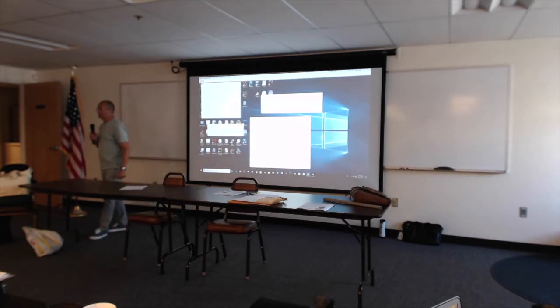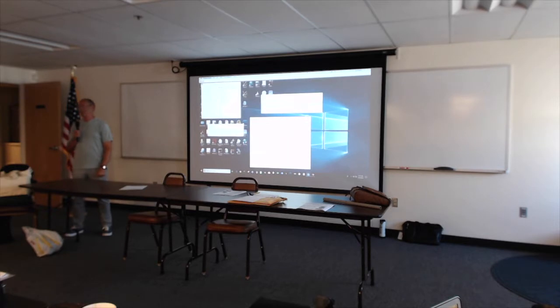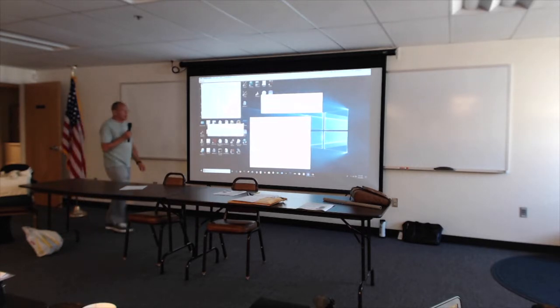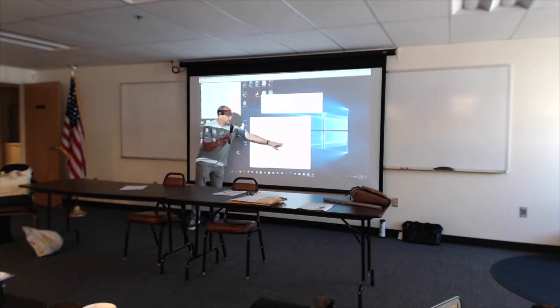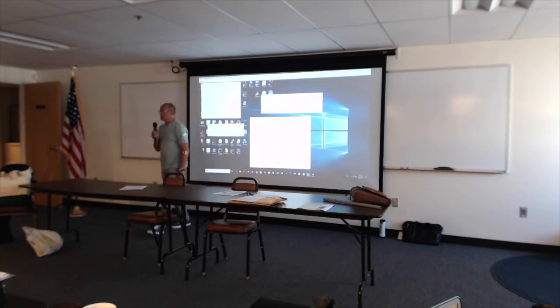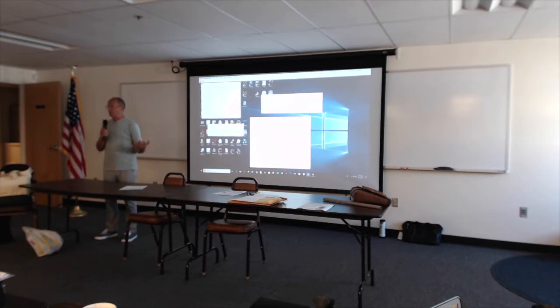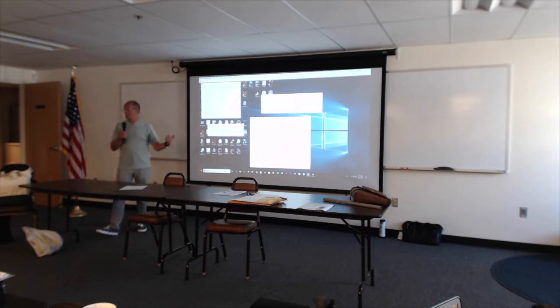Yes, sir. Tom, this may sound dumb, but was there a reason that you feed it from a corner and not from the center or the bottom? Yeah, I went through many iterations of this model, and I put the connection in the center here, and the plots just, the SWR, I couldn't get it within a reasonable range, at least according to the software. If I'm not mistaken, on a delta loop, that's what this is, if you feed it in a corner, it's going to give you a vertical polarization. That's right. If you feed it in the middle, it's going to give you horizontal polarization.